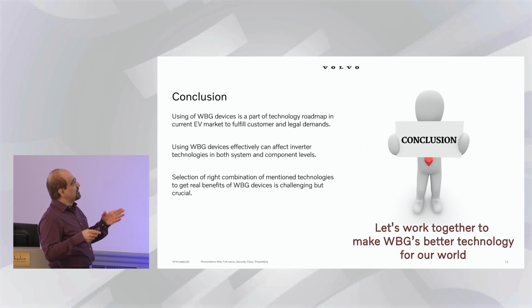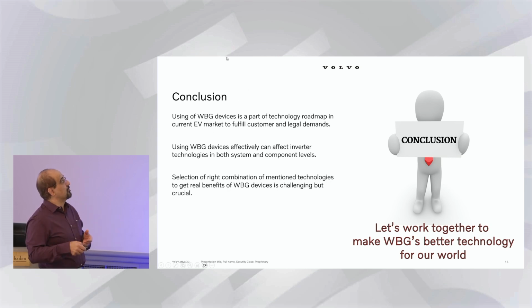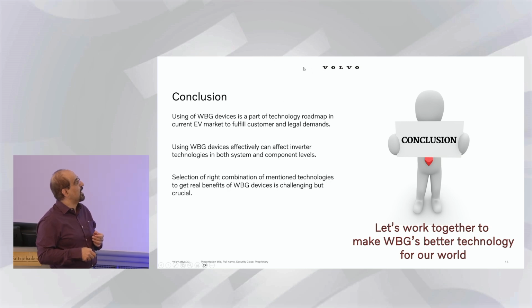I can say that using wide-bandgap devices is a part of the technology roadmap that we have, and everybody is using it. But there are a lot of challenges to fulfill customer and legal demands. Using wide-bandgap devices can affect many technologies: the DC link cap, the EMC filter, the bus bars, the gate driver, the topology that we are selecting, the architecture that we have. All of them can be affected.